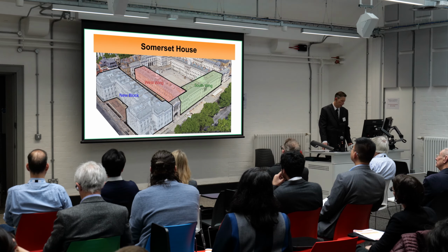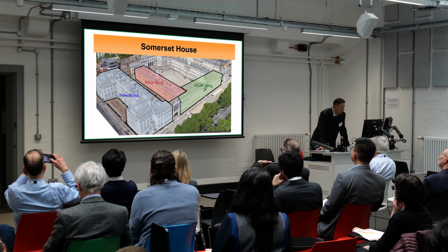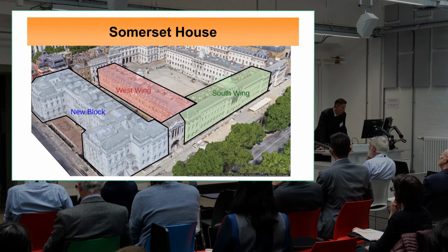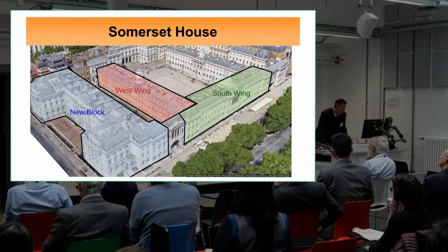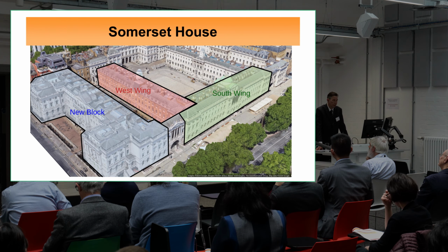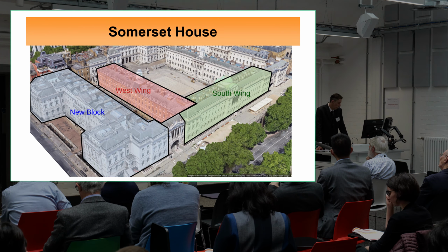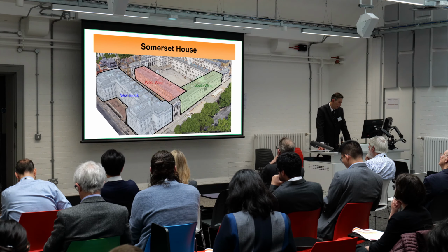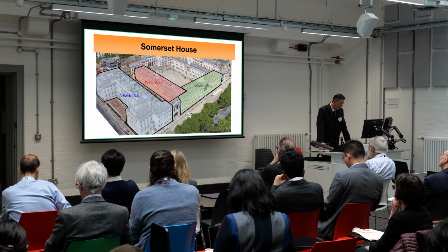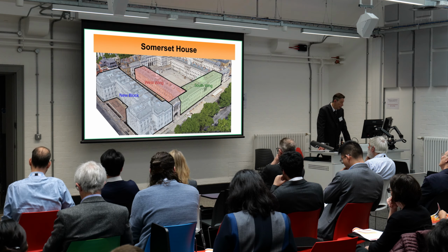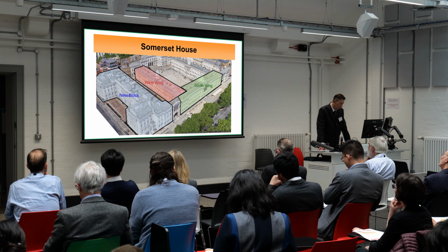Second example is Somerset House in London, which is a Grade 1 listed 18th century Georgian building, with CHP and boilers providing heating to 6 VT circuits which feed 350 cellular offices and various corridors, WCs, etc. And you can see the wings that we fitted the controls to. So we fitted around 750 wireless TRVs and 350 room sensors with temperature and motion into these 3 wings, which are each 6 stories high.